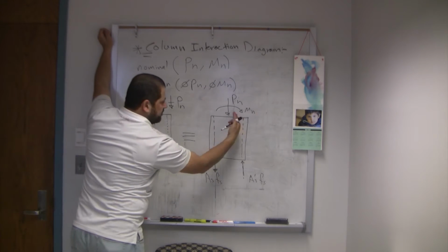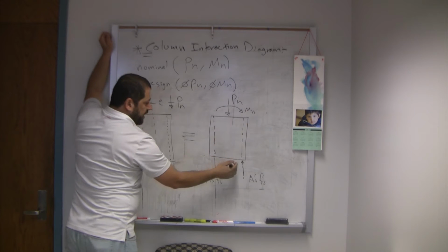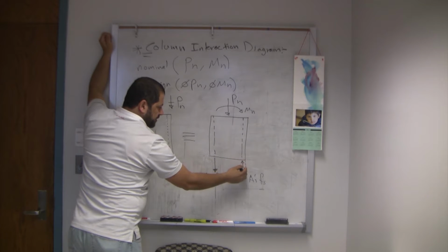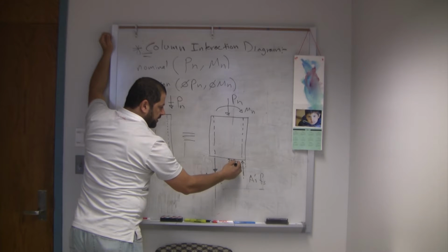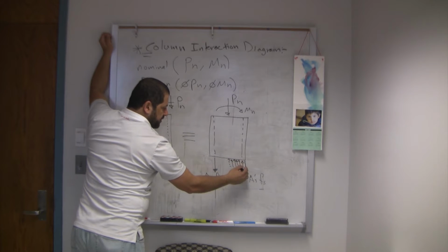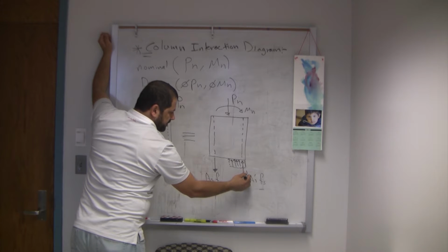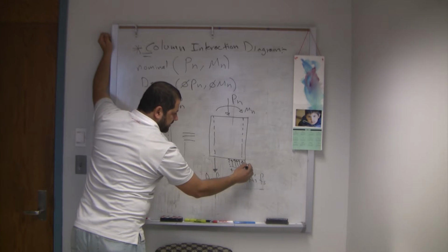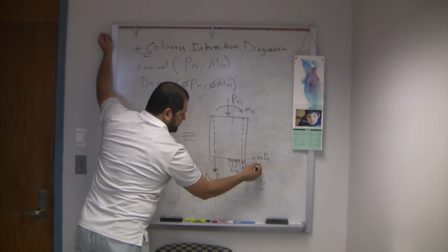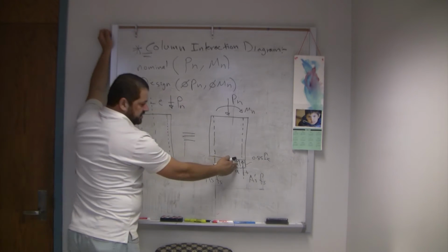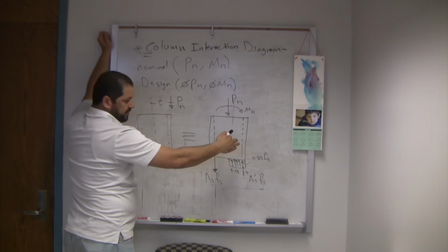This is the steel on this side. And you will have the equivalent rectangular area for the concrete. As you know, this is a, and the stress is 0.85 f'c, and remember, this intensity is over the width of the beam.